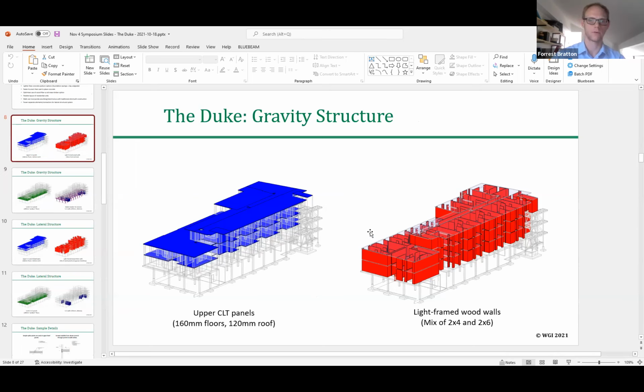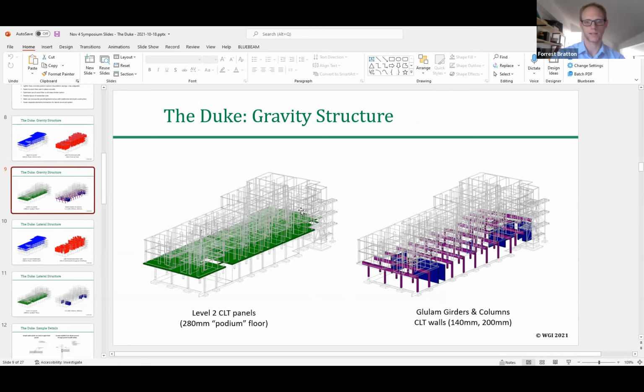And so the upper floors, we've got CLT panels at the roof and upper floors. That load's coming down in our bearing walls within and between apartment units. And then below that, all of those bearing walls are getting picked up by this heavy CLT plate and then spread out to beams below that don't match up with the demising walls and bearing walls above. And so because we had several floors worth of load building up onto this single panel you see here in green, the project was particularly sensitive to an extra 5 to 10 pounds a square foot per floor,